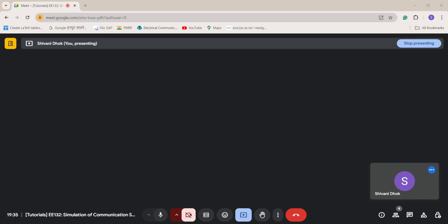The first row of D all contains the difference between the first entry of Y and all four constellation points. Now I need to select the index of 1, 2, 3, 4 that gives me the minimum of them. So from this particular row, I want the minimum distance, which is 0.9335. Similarly, from the second row, I want this particular value.